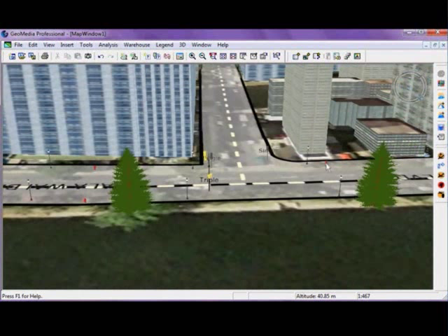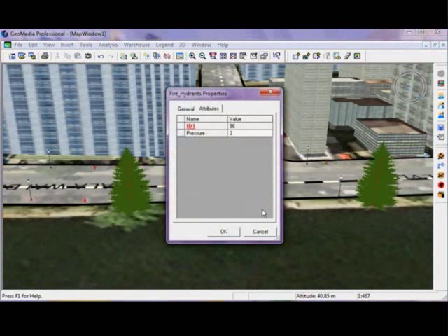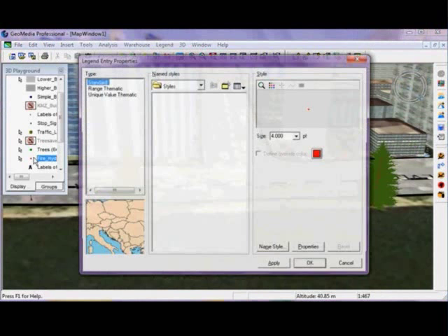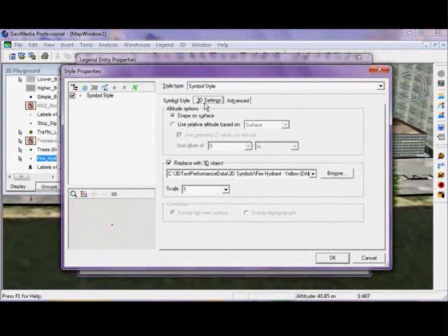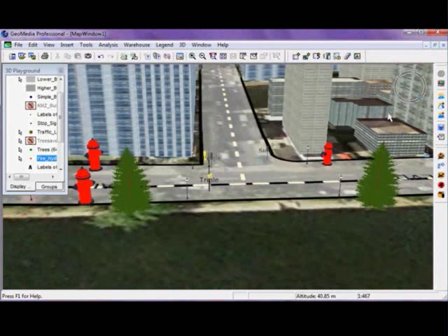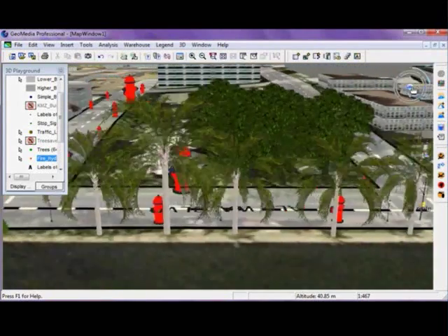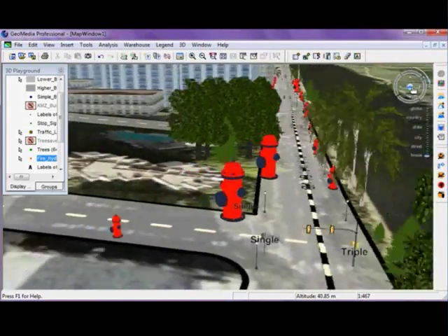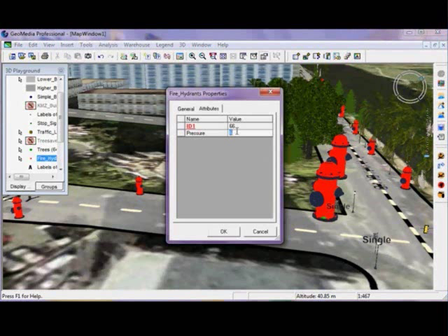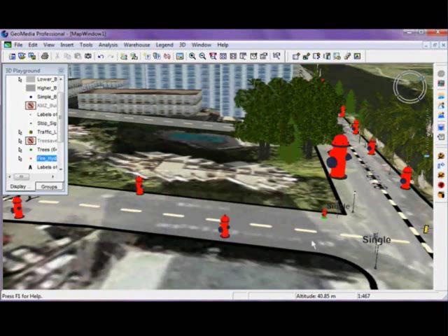And then we'll just take a quick look at the fire hydrant. I have some pressure information. So if I wanted to graphically depict what the pressure would be like, let's say, across the downtown area, I can go in and use that pressure to extrude. And then what I'll do is I'll just exaggerate it times 2, just so we can see it for the purpose of this demo. And then it updates and extrudes my fire hydrants based on that pressure reading. So we'll take a look at this one. We'll change it back to a 1, and you'll see that it adjusts dynamically for that.